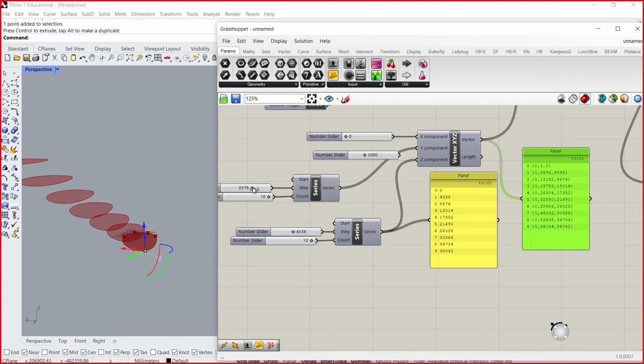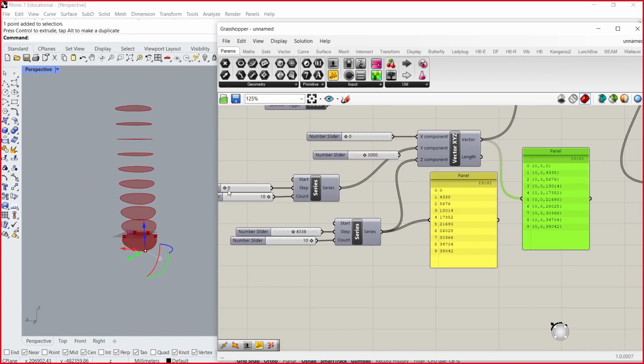And you can see hopefully here the vectors are changing. So 0 on the X, and this Y value changes based on this. Okay. So if you really know how to use these nodes properly, you can go on and use any plugin you want in Grasshopper, right? The issue when working with Grasshopper is you jump into plugins without knowing how to use Grasshopper properly, and then you get confused. So all these basic things we're doing are very important.